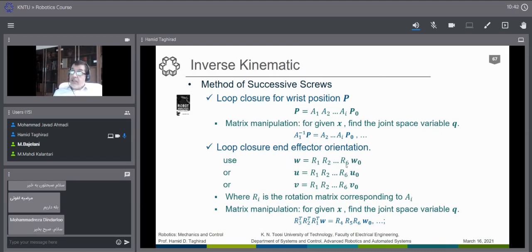In this orientation, as you see, we have all 6 R's here. We don't need the homogeneous transformation for orientation. We can use only the rotation matrices here. And since in the first part we have found the first 3 or 4 parameters, we can take these 3 or 4 now-known rotation matrices and bring them to the left-hand side. This is totally given now, and this part is not given. And then you write the equation here and try to solve it by rigorous mathematical inspection.